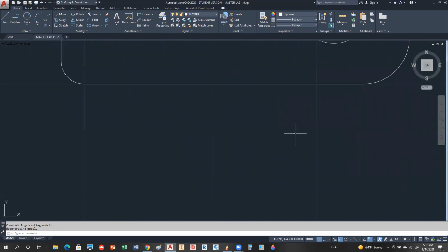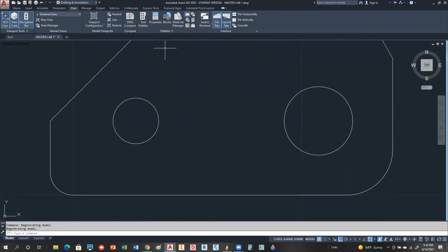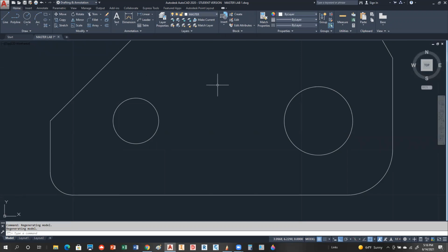That's where the zooms come in, in AutoCAD. You have more control. You have this whole section here called Views, and they've got zooms built into some of this, but I'm going to show you that zoom is a lot easier to just do by typing. You can do some of the zooms over here too. Those are zooms right there, and there's a bunch of different ones. But again, it's simpler if you just type in Z.